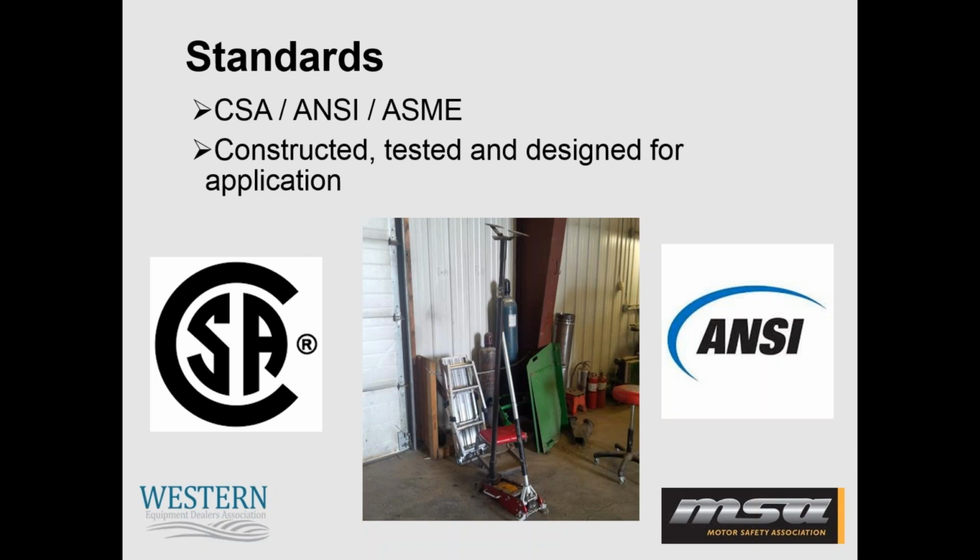I knew of one farm equipment dealer group that built their own type of stand that they've used for jacking sprayer wheels, and they had those approved at PAMI, and now they resell them at their dealerships. So again, just keep those types of organizations in mind when thinking of standards and knowing that your lifting devices and jack stands do meet an applicable standard.